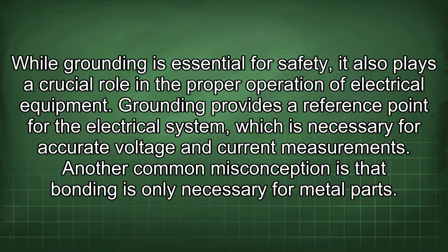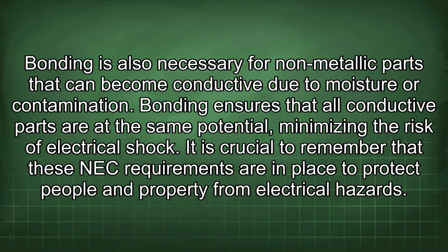Another common misconception is that bonding is only necessary for metal parts. Bonding is also necessary for non-metallic parts that can become conductive due to moisture or contamination. Bonding ensures that all conductive parts are at the same potential, minimizing the risk of electrical shock.